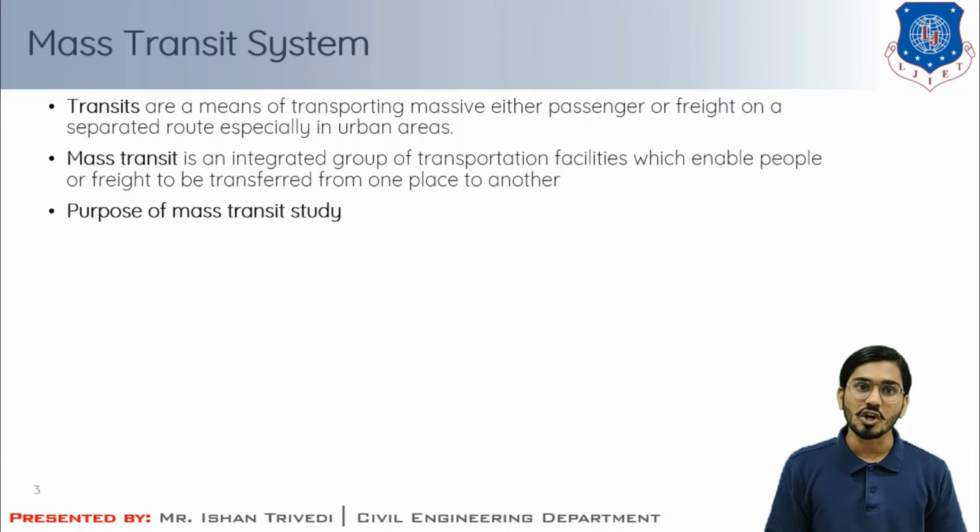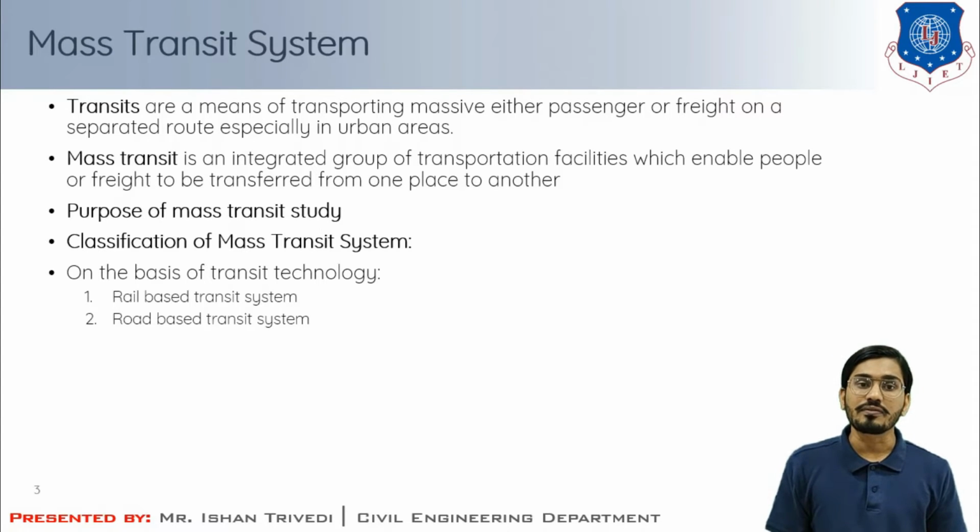So first, we have to understand the purpose of mass transit study. It is important to assess the quality of existing transit service, to study the operations, problems and the location of stops, and that's why we require mass transit study. It is also needed to establish the extent of usage and determine the vehicle types and various routes, then to obtain the characteristics of mass transit riders, then to plan, design and operate mass transit services, then scheduling of these mass transit services, then to conduct an economic analysis of public transportation and various operations which have been carried out for this public transportation and their improvements.